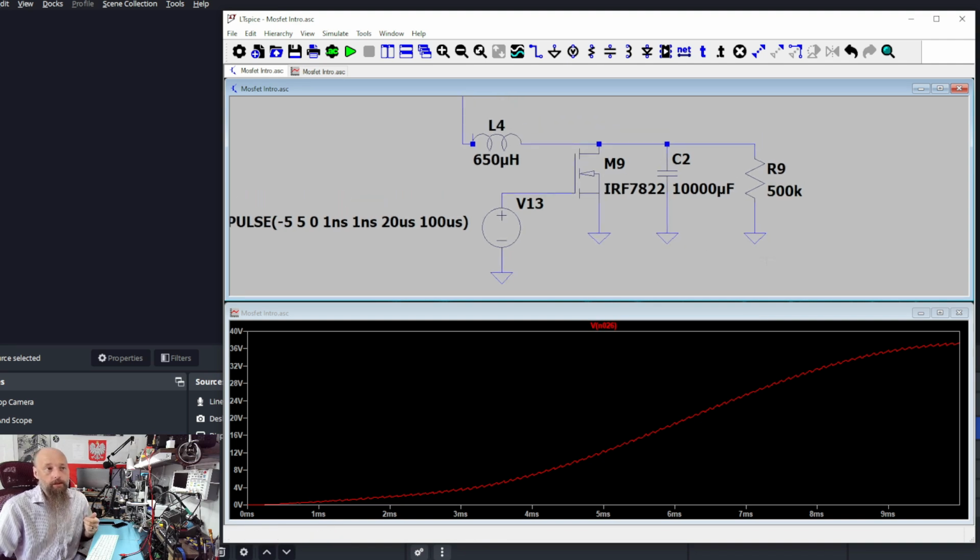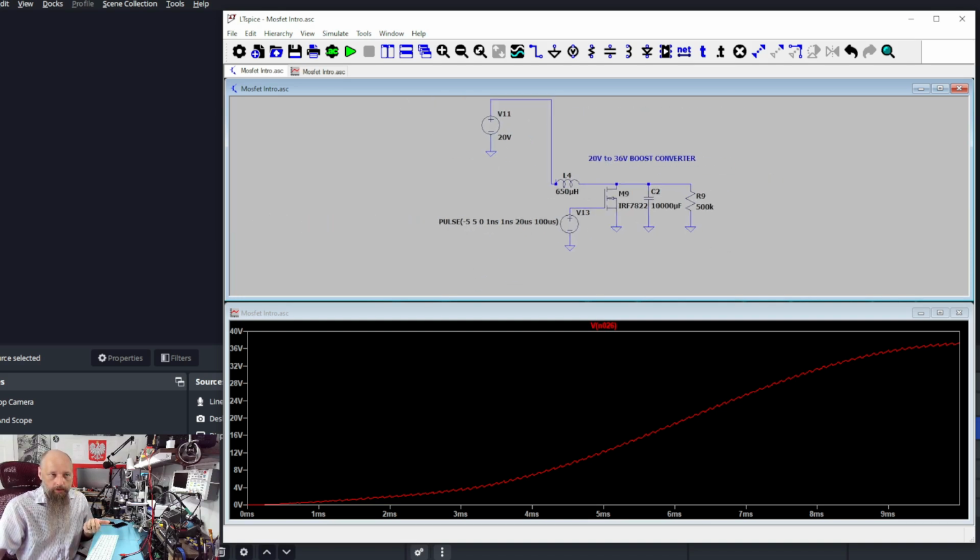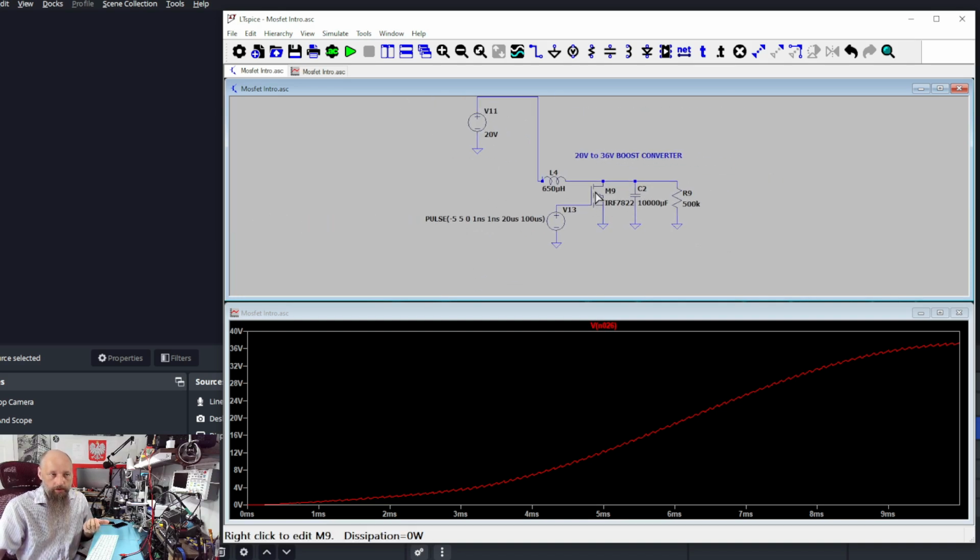We just connect the coil to the ground for just a little bit, just enough for the coil to start to charge, and then we stop the flow, the coil discharges, increasing the voltage. For that reason, there's no way to reduce the voltage, because even if we completely remove the transistor, we're going to have input voltage on the output.